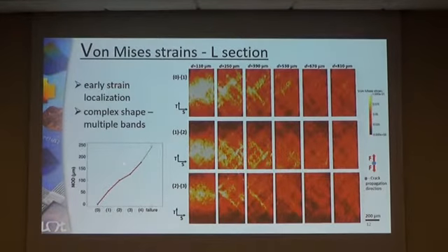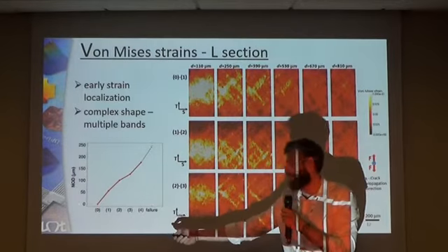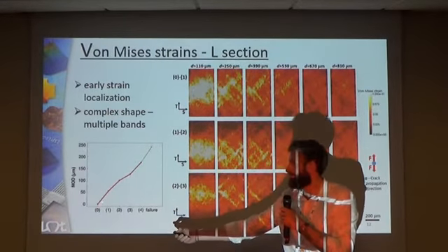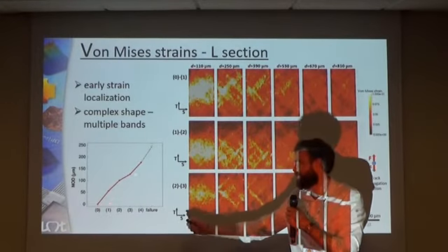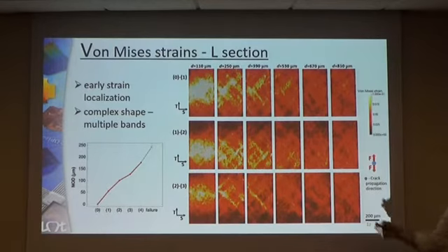Okay, on the left here, you can see notch opening displacement as a function of this stepwise loading procedure. After the first loading step, in the undeformed configuration, we have scanned the material, and we have additional 4 scans after each of these loading steps. Since we have really complex kinematics that develops in front of the notch root in the immediate vicinity, successful DVC calculations have been obtained for the first 3 incremental loading steps. And these 3 loading steps are shown here: the first, second, and third incremental loading step.